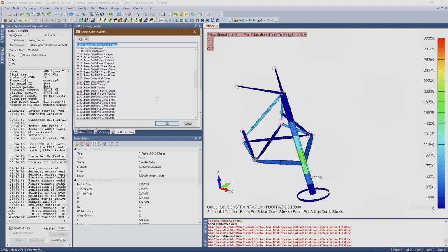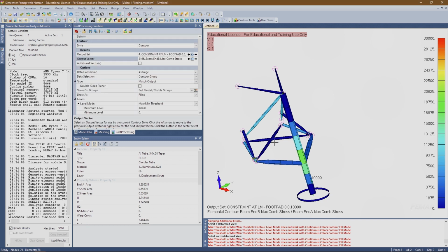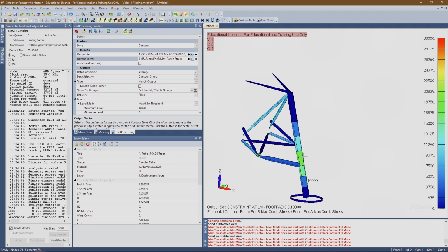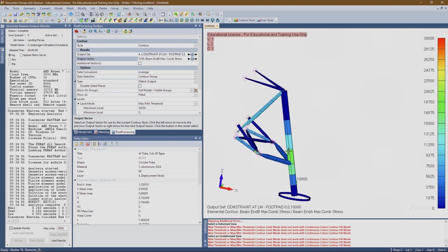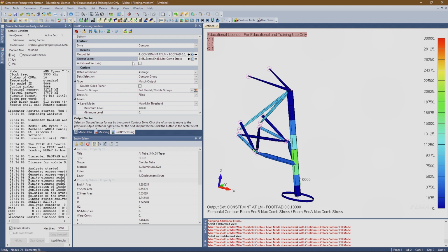Worth noting, beams do not do torsional stresses, because torsional stresses in anything except circular tubes are generally very messy solutions. Like I said, beams calculate exact stresses using the theoretical equations. So torsion generally doesn't have those.